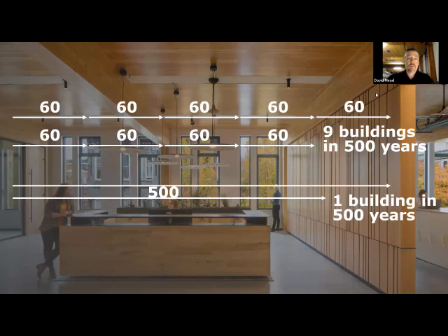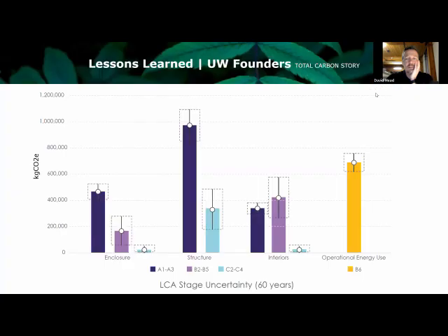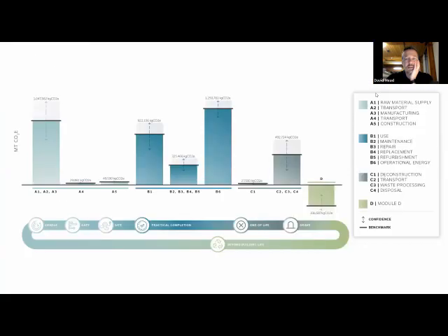So one of the main concepts is to rethink that, so that when you look at a longer time horizon, you're not letting the end-of-life aspects dominate it too much. And I'll show you why, because often at end of life, if you've got a wood project, for instance, the way that an LCA accounting process works in the US is you might be able to take credit for the sequestration of the wood materials in the A stages.